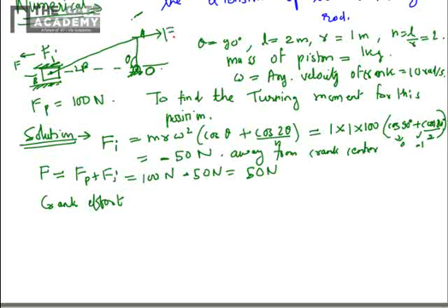It is Ft, crank effort Ft. So the formula for Ft is, as we saw in our derivation just now, F by cos beta sine theta plus beta. Now for that we have to calculate the angle beta. Theta we already know, it is 90 degrees.